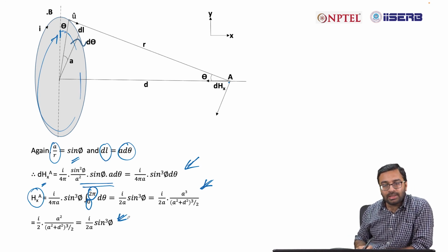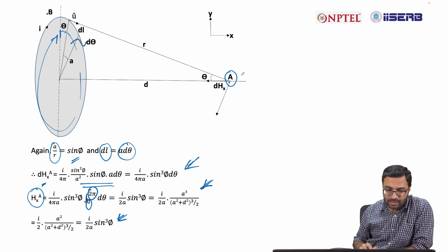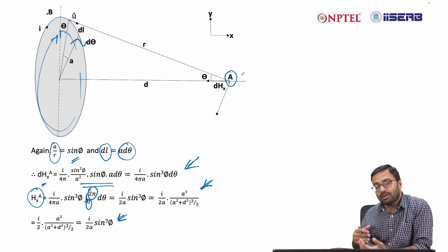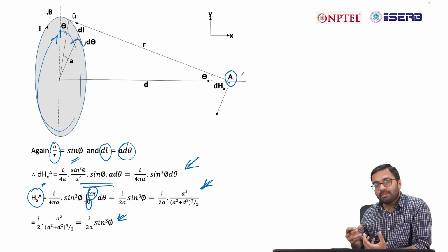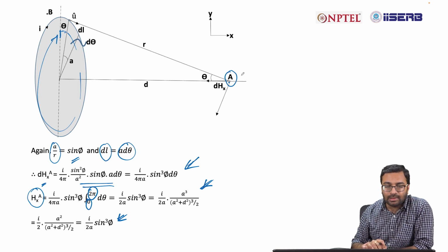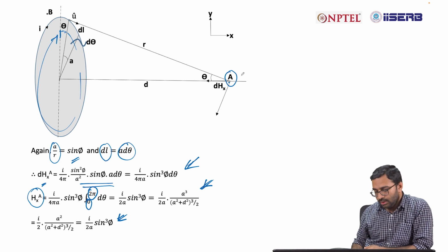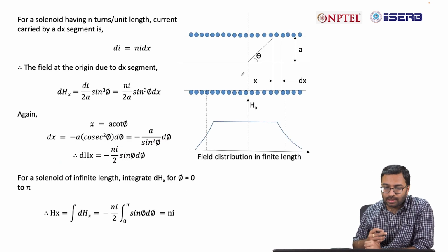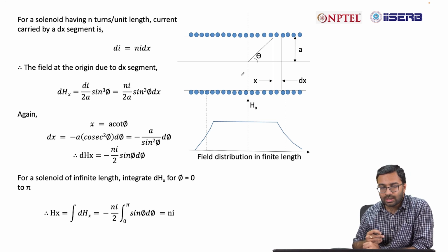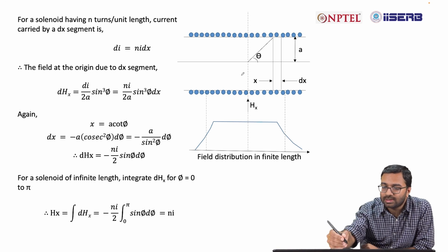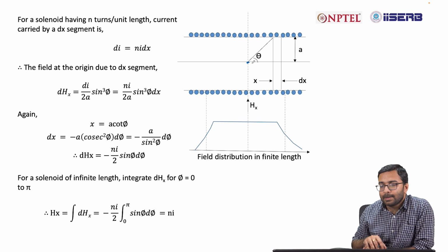So, this is the value of magnetic field at any distance a, and again it is a function of the value a and sin phi. So, you can very easily calculate the magnetic strength, just in case you are planning to use any magnetic sensor that can be used for various purposes. If you use the same calculation for a solenoid and you try to calculate the magnetic field at any point inside the solenoid, say here, then also you can utilize the same equation.